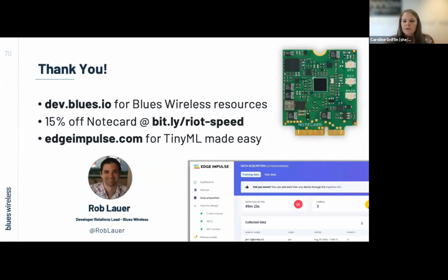And then Paul also wanted to know, do you know the frames per second? So the frames per second from the video was 10, and that was all about finding the happy medium for grabbing a frame and doing that processing with the Edge Impulse runtime. I wanted to make sure that I wasn't going to overrun the runtime with a bunch of frames. So that took a little give and take, because ideally you want to process as many frames as possible, but 10 I found was pretty good.